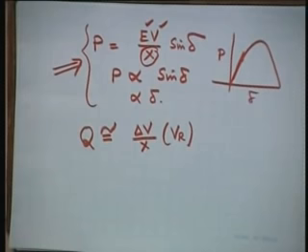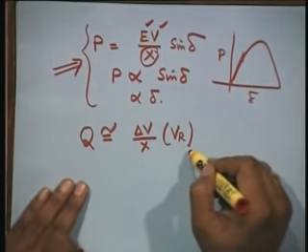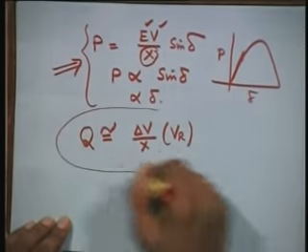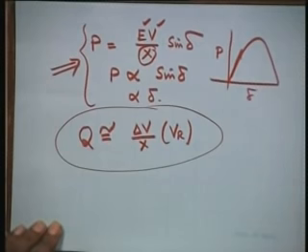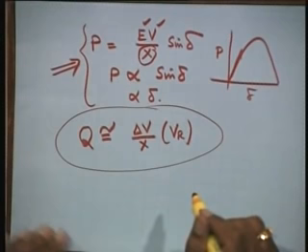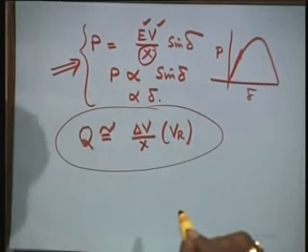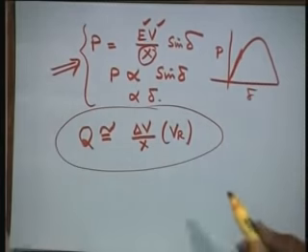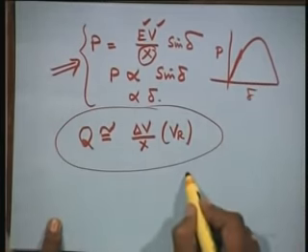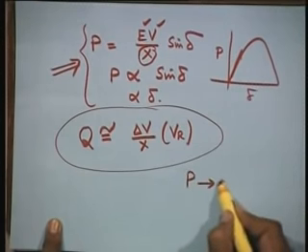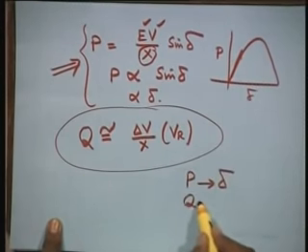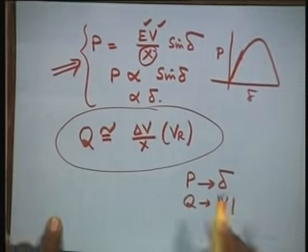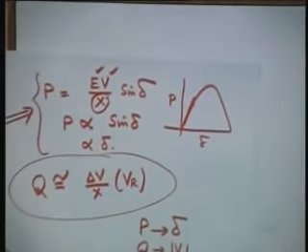But when it is approximated, the delta dependence goes away. In fact, the cosine delta term is there, but delta is small, so cosine delta becomes 1, cosine 0 is 1. So, this is proportional to voltage, and that is why my famous decoupling principle is P is close to delta and Q is close to V. Using this, what have I done?